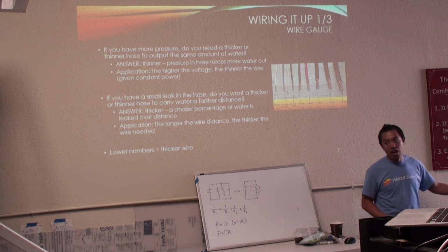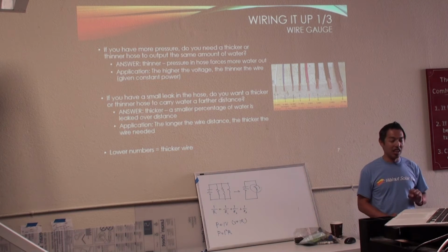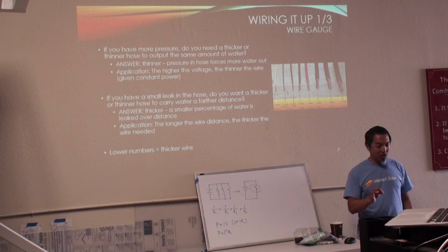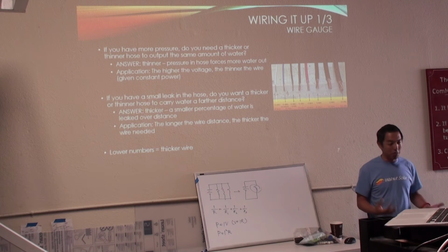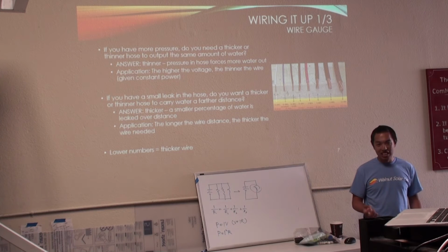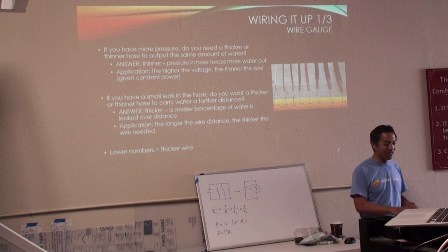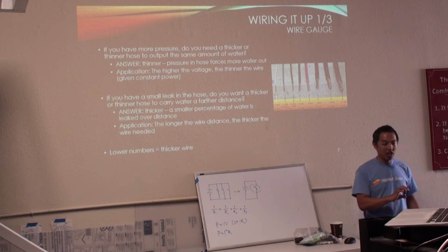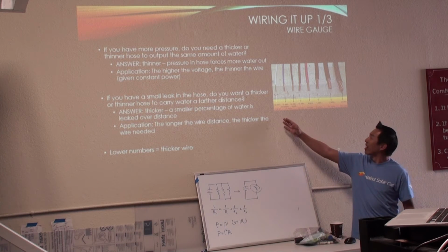This is why in our drive wiring, you need thicker wire because you're going to drive a whole bunch of current through it. Whereas all our supplementary stuff, because they take 1 amp, half an amp, maybe the little fans take like 0.1 amp, they're really low current draw. You can use very thin wire.